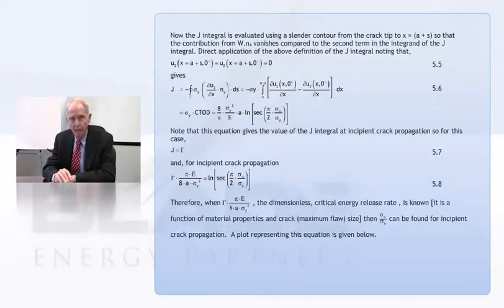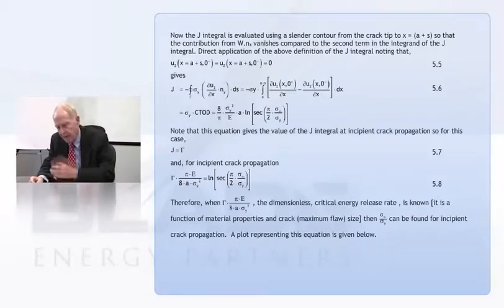And that's going to be our contour. And when we do that, you have to imagine that you can make that contour as close to the boundary of the crack as you want. And so you just put it right at the crack. And that means there's no real area there, and consequently there's no strain energy. So you lose that term.